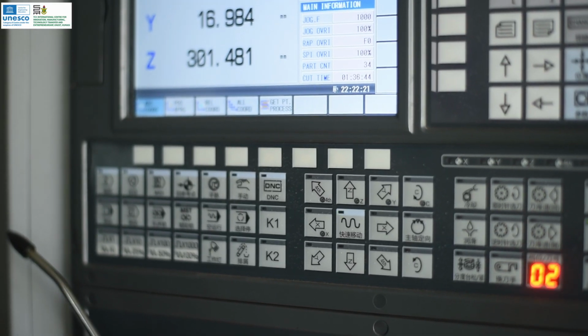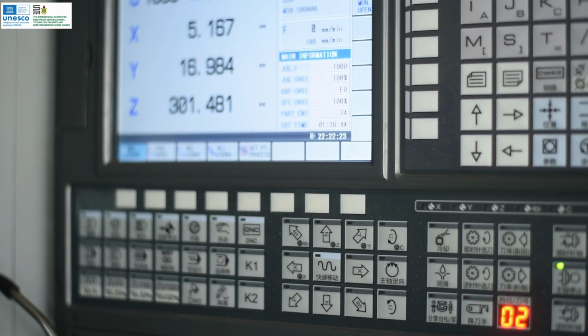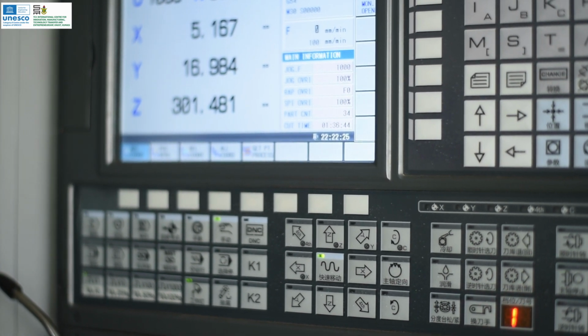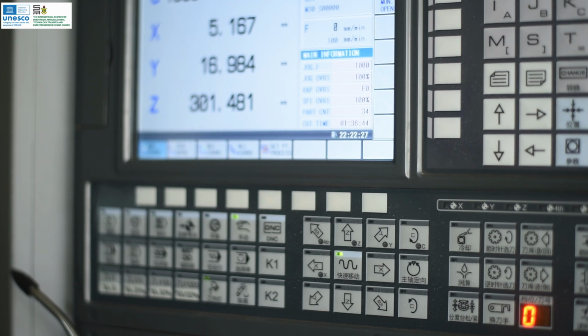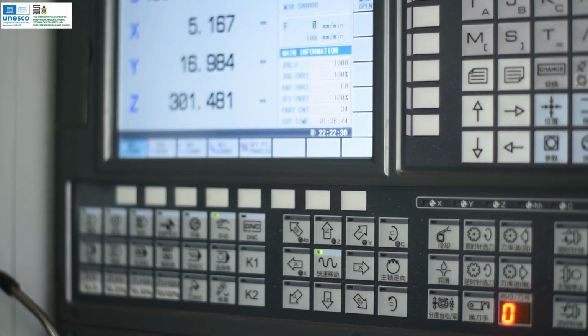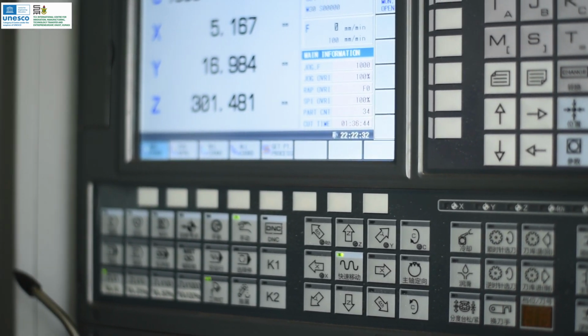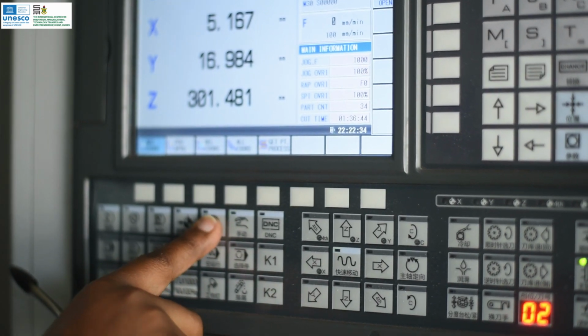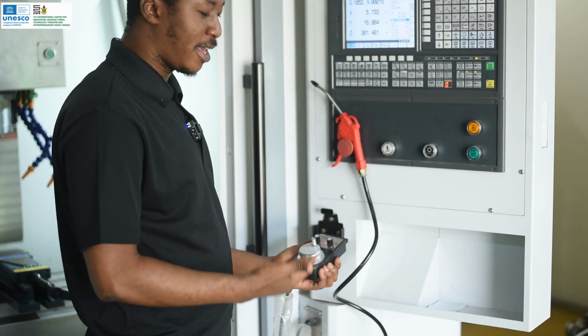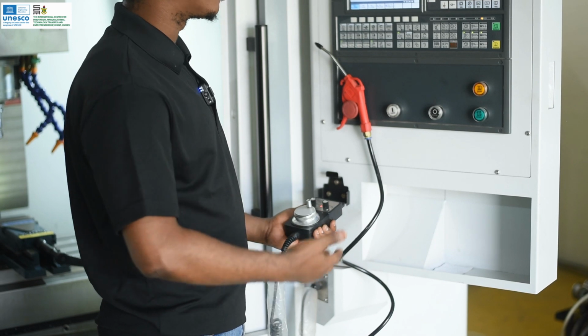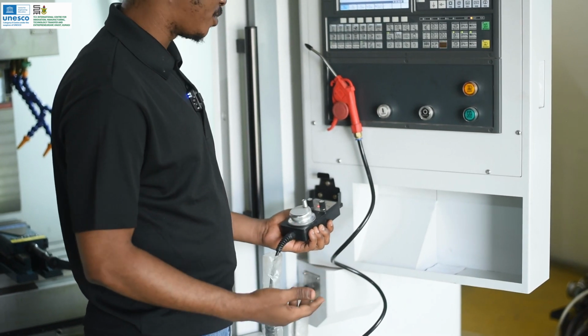While in manual mode, we have coarse control over our machine, and if we wanted finer control, we could press this button to put us in pendant mode. That allows us to use the pendant that came with our CNC machine to control the axis of the machine.